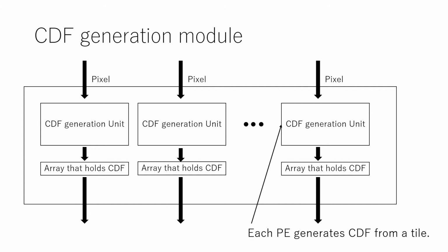In the histogram create loop, we can set loop interval 1. Because our target low-end FPGA cannot meet the target frequency, we set loop interval 2. But our structure mitigates this effect because the processing can proceed in parallel.